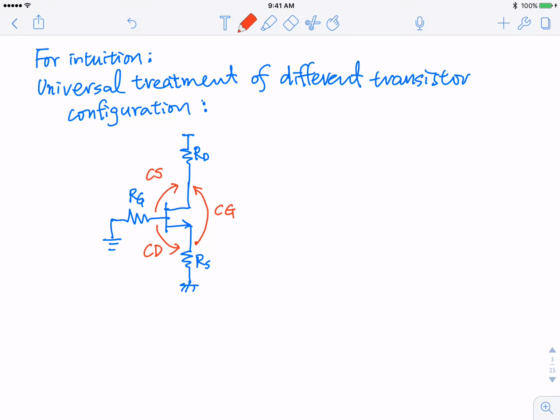Okay, all fine. So the next thing is, obviously there is gain associated with that, and you have analyzed the gain. The gain is also very generic, that you can more or less keep in the back of your mind. For CS, this will be primarily voltage gain, and that will be minus gm R0, okay.